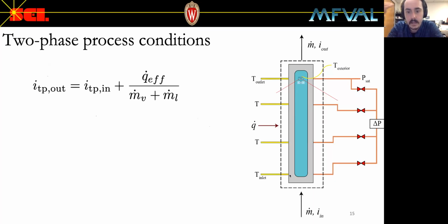And do you know how small is small enough, if you had a thermocouple junction there? Yeah, it's on the order of microns. The liquid film thickness typically is on the order of 50 microns to 100 microns. And when you're heating, it gets smaller, like 30, 40, 25, really small. So anything that's bigger than a few microns would disrupt the flow.